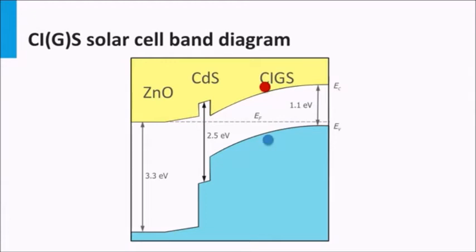a heterojunction. The light-excited minority electrons in the CIGS layer have to diffuse to the cadmium sulfide-CIGS interface to be separated. The holes diffuse to the molybdenum back contact to be collected. Here, the holes recombine with the electrons supplied from this molybdenum back contact. Zinc oxide acts like the front contact. The band gap of the zinc oxide is very large, minimizing the parasitic absorption losses in this device.